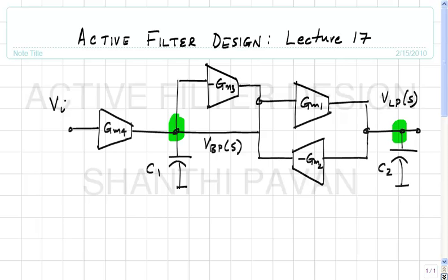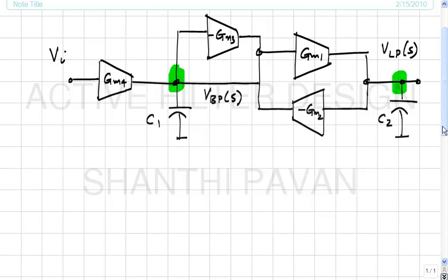we also concluded that since we now know how to make a second order section, in other words a building block which will give us a second order denominator and a numerator which is some constant k, we can in principle cascade such building blocks in order to realize any arbitrary transfer function where the numerator is a constant, correct.